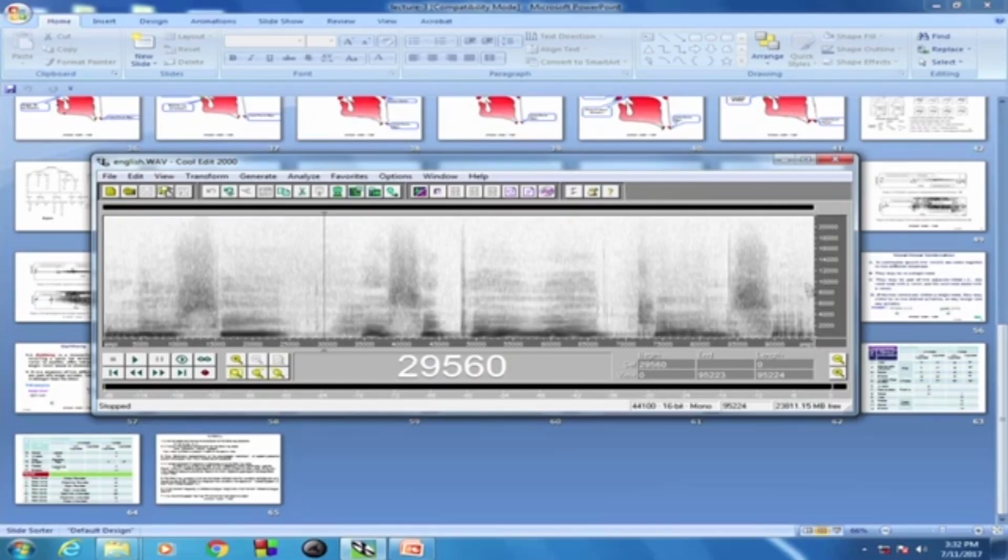This y axis is the frequency axis. So, this is 2 kilohertz, 4 kilohertz, 6 kilohertz, 8 kilohertz. The sampling frequency is 44 kilohertz, so up to 22 kilohertz, fs by 2, it is there. Now, the black portions contain the high power. If I say within 2 kilohertz most of the sections are black, that contains the high power.